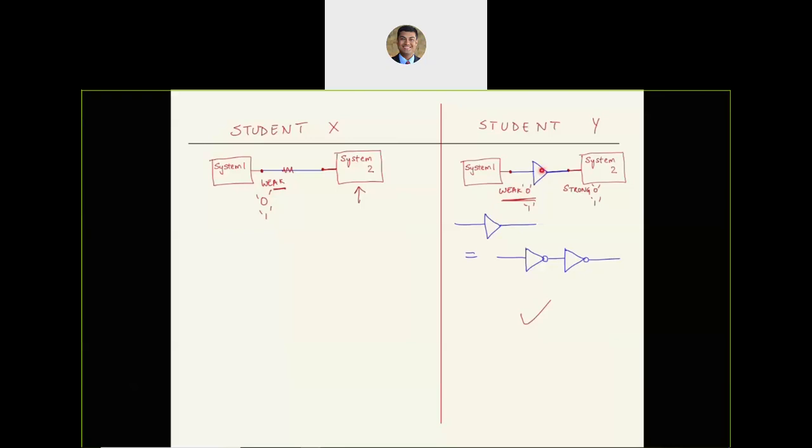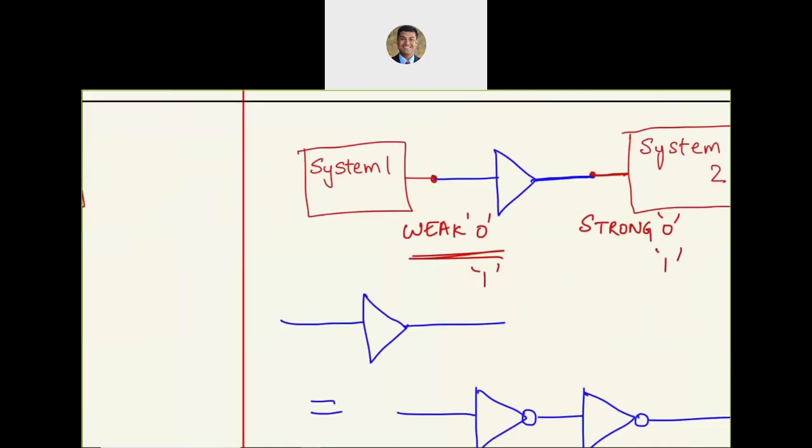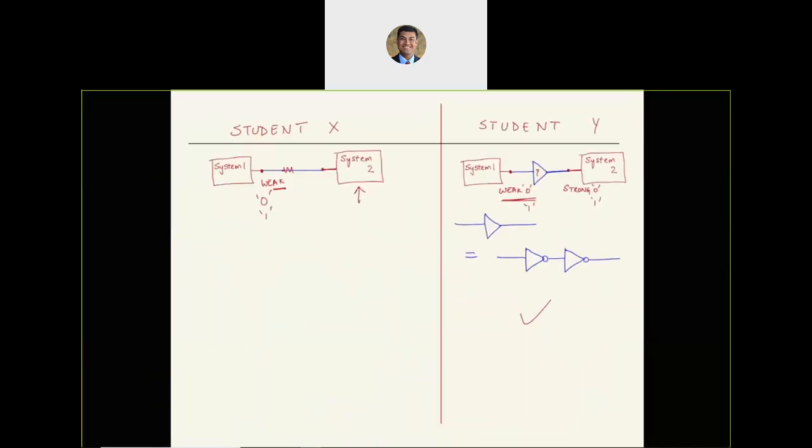So that's essentially the use of a buffer. Even if it doesn't do anything, y equals x, it is still able to give us this usefulness. We can use this as a bridge, since the second can change the weak to the strong. How it turns weak into strong, we are going to see when we look at what is inside. That question will be answered when you look inside the buffer. So just hang on to that question. Right now just assume that it does that. It has to do with what is inside, and we'll address that in a few minutes.